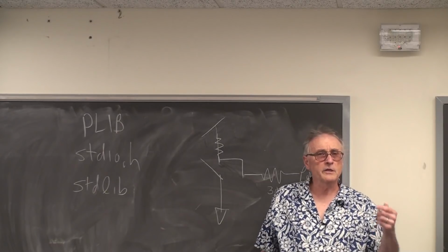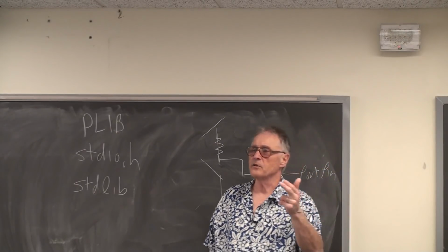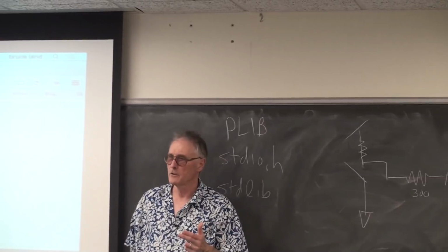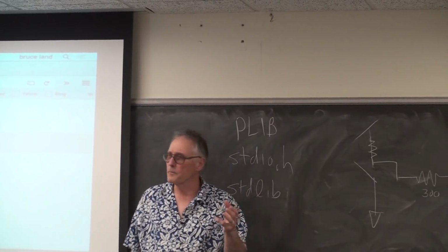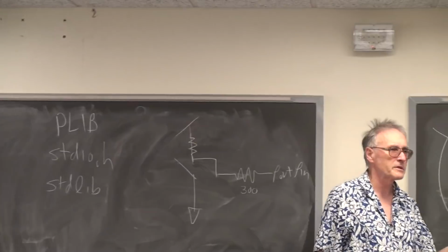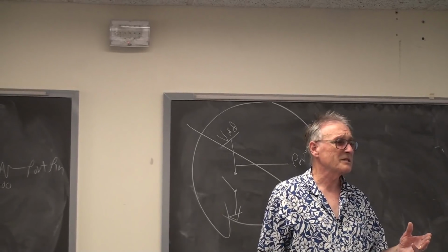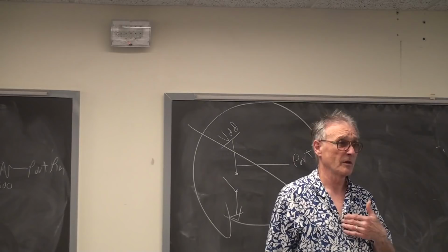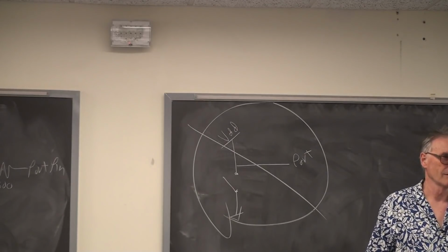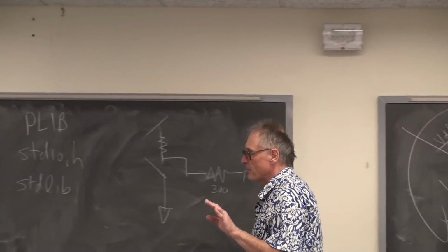So you can take the base frequency of the internal oscillator, which is 8 megahertz, and you can set it to any rational fraction up to about 80 megahertz in steps of 4 megahertz or so. You can set it to any frequency you want. The output of the phase lock loop can be higher than the input frequency. And in fact, you can set it so high, the CPU won't run. Because some variants will run up to 80 megahertz, ours won't. Ours is guaranteed to 50, but it runs at 60 often. Now, if you drop it in ice water, it'll almost always run at 60. But on the tabletop, you're guaranteed to have 50 megahertz.